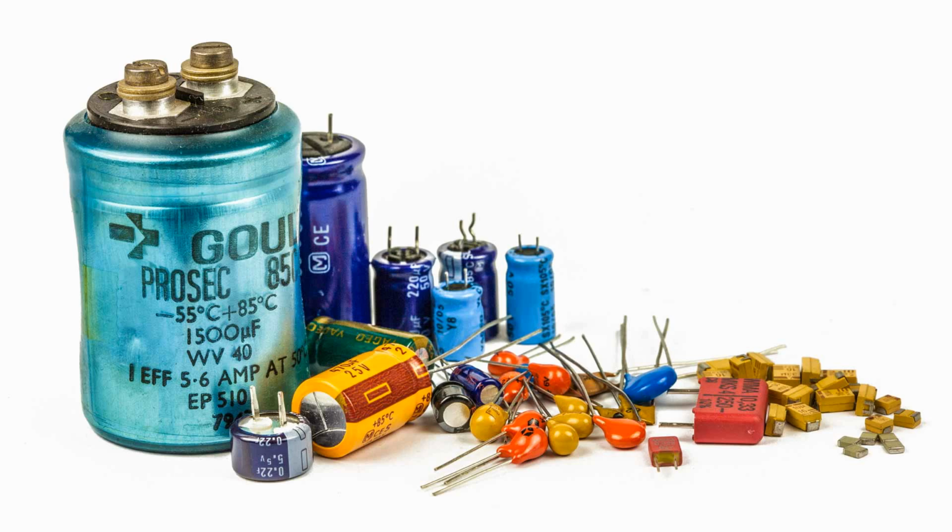Advantages of using capacitors for filtering. Frequency selectivity. Capacitors can be easily adjusted to filter specific frequency ranges, making them versatile in various filtering applications. Low insertion loss. Capacitors have minimal impact on the desired signal, ensuring that the filtered signal retains its quality. Compact size. Capacitors are relatively small components, allowing for compact filter designs in electronic devices.